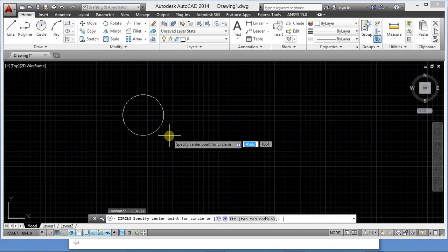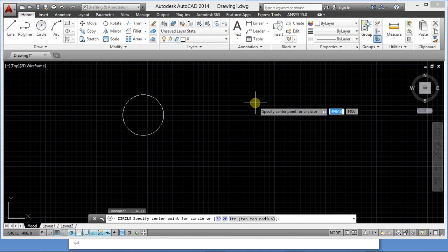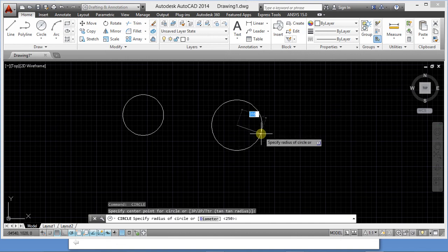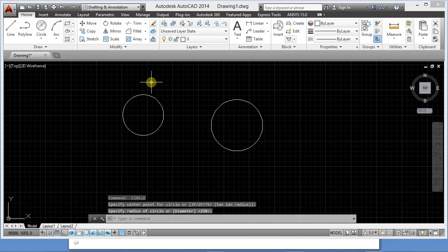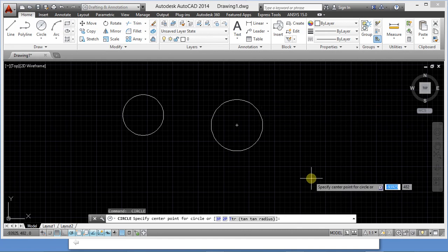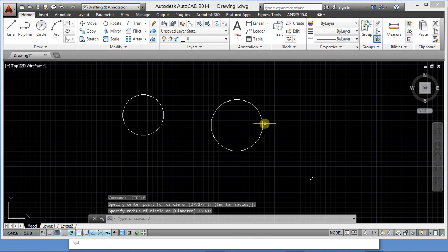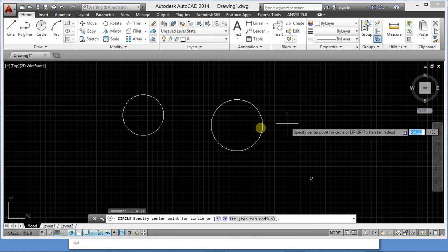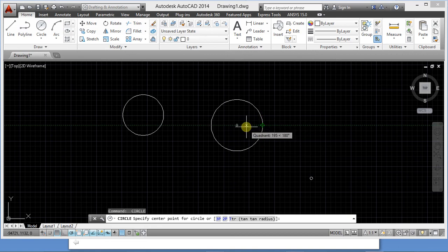After you specify the center point, you specify it. Now, assuming I want to get the center of my circle, I'll activate the circle tool. If I hover my cursor at the line, you will see the midpoint. Assuming you want to draw another circle from the midpoint, just hover your cursor on the circle. You will see the midpoint. This plus shows you the midpoint.